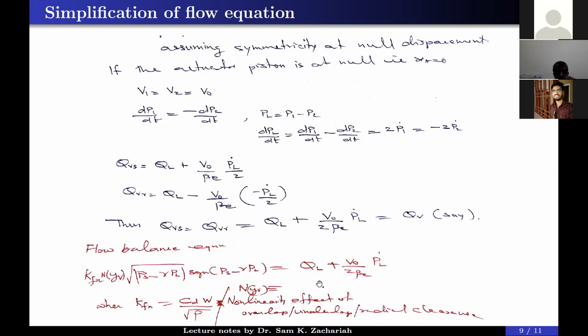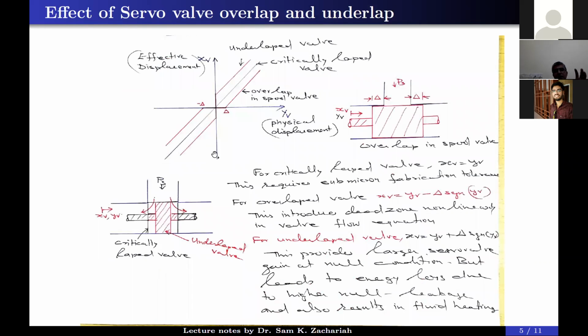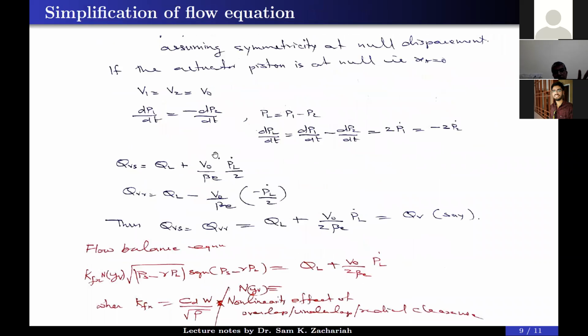Now the consumption side, load flow plus compressibility flow. So with respect to this system, here we are connecting the servo valve. Servo valve is actually interfacing the supply of the fluid to the load. So one part of the flow is whatever is generated, and the other part of the flow is what is consumed. So generated flow is equal to consumed flow. Generated flow is due to the servo valve equation we derived, and the consumed flow is due to the load flow plus the internal compressibility. So this completes the hydraulic flow path. Any doubts on this?